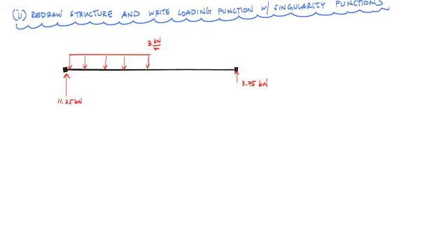And I also want to draw the coordinate system to remind myself which way is a positive deflection, which way my x-axis is going, and where my origin is. Here this V indicates my deflection. Anytime the beam moves upwards, that's considered a positive deflection, whereas if my beam goes down below the x-axis, it's a negative deflection.